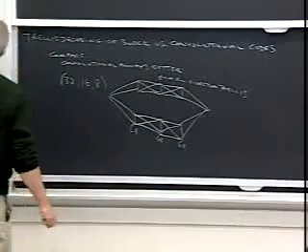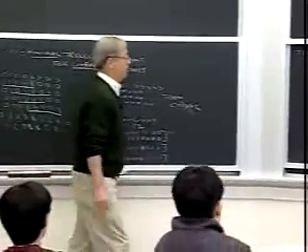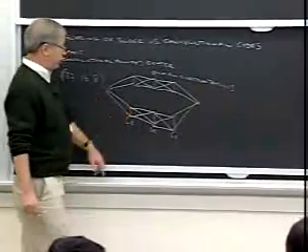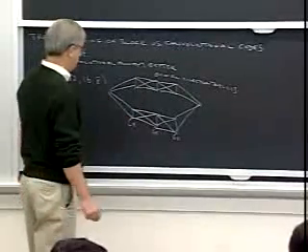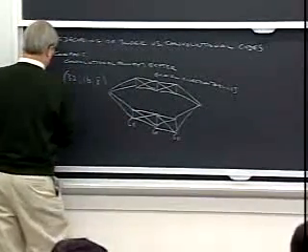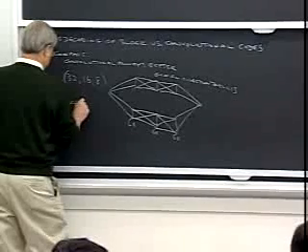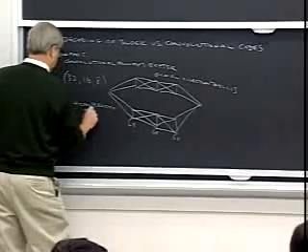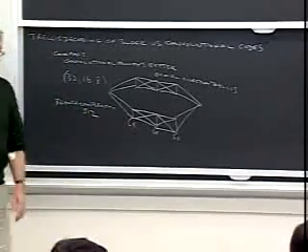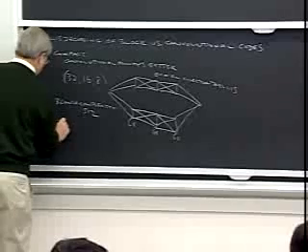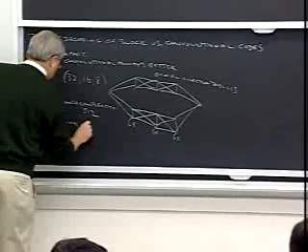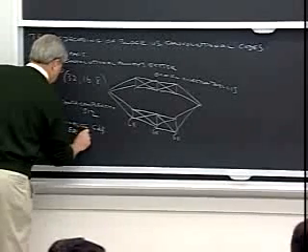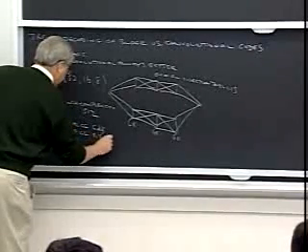But if you're more honest, just exactly as with the Golay code calculation we went through, you find that the maximum branch complexity is 512. So its branch complexity is 512. Okay, and its nominal coding gain, we said, is 6 dB, and its effective coding gain is 4.9 dB.